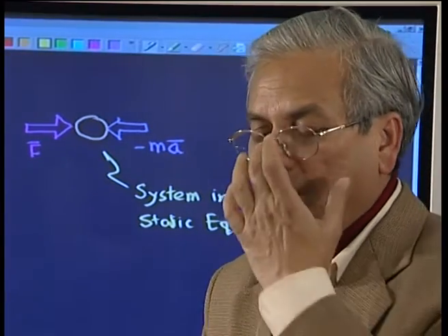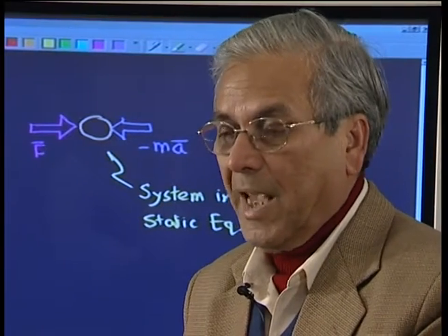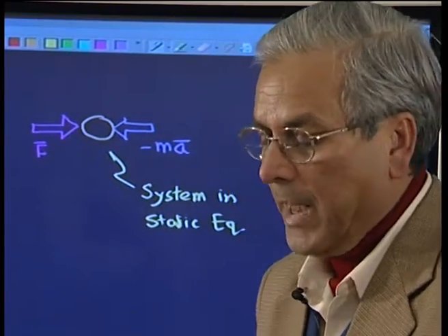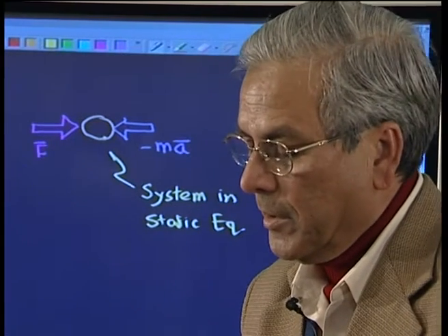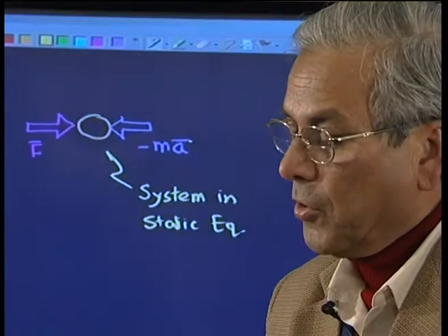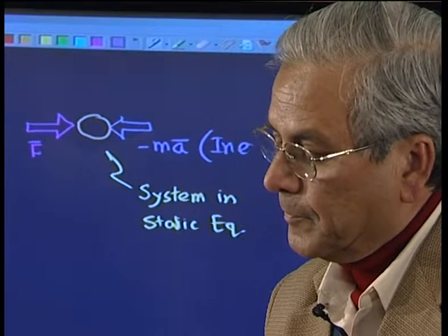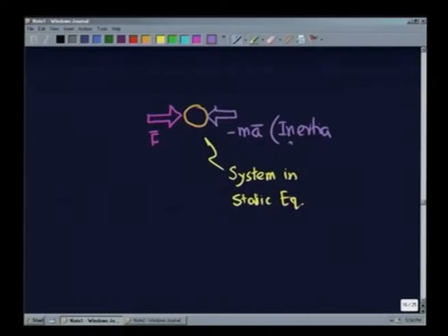So, this is D'Alembert's principle, though it is not as trivial as it sounds. It says that if we subject the body to the actual external force along with a hypothetical force which is nothing but minus m into a, which we call inertia force, the body will be in static equilibrium.